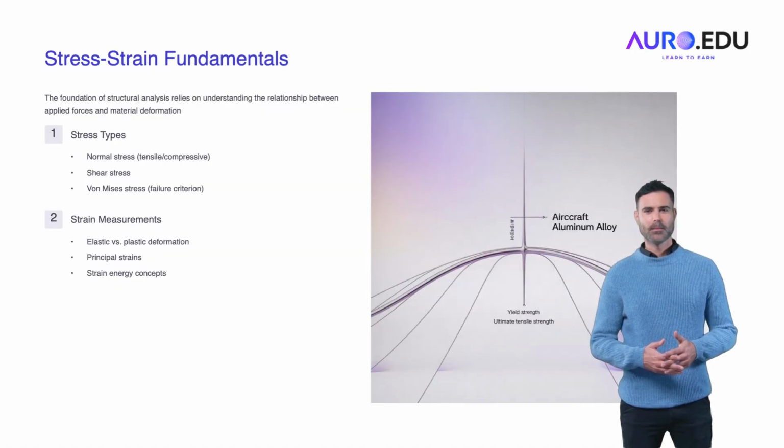Stress-strain fundamentals. The foundation of structural analysis relies on understanding the relationship between applied forces and the resulting material deformation. Stress is defined as the internal resistance of a material to deformation, and it comes in several forms: normal stress, tensile, compressive, and shear stress. The von Mises stress is a critical factor in predicting failure, as it combines multiple stress components into a single value that indicates when the material will fail.